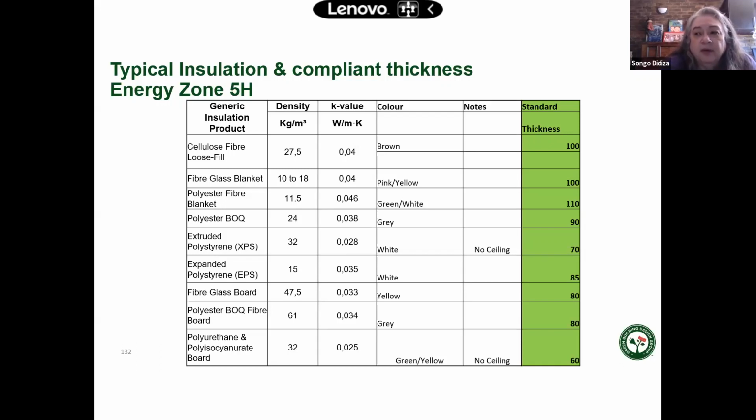And if you can see the light, that means the air is just flowing through it. It has to be quite dense. And it could be to do with the density of the material. That's why I put densities there as well, because obviously the denser materials have different thermal conductivity values, and maybe you'd have to go to a thicker value.